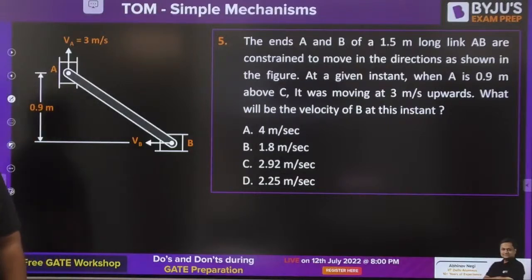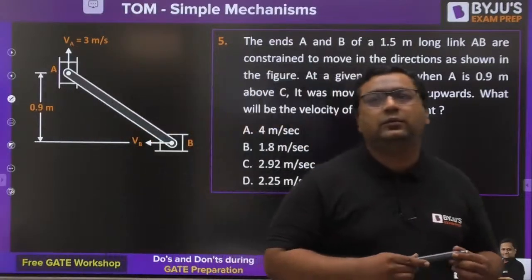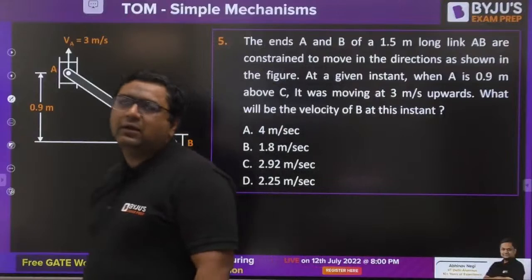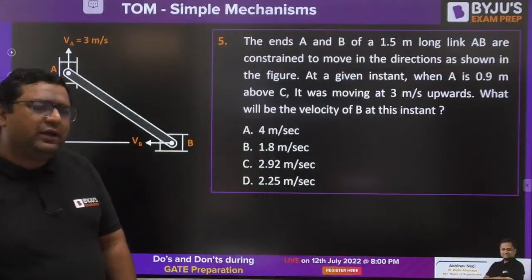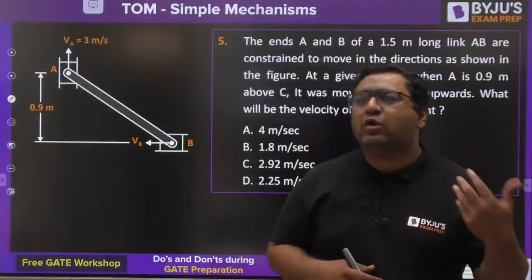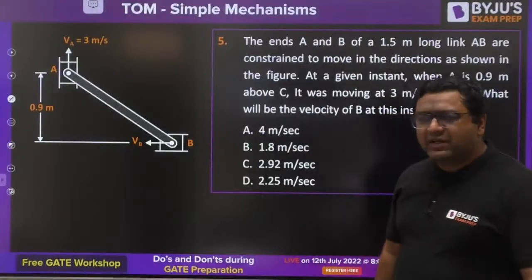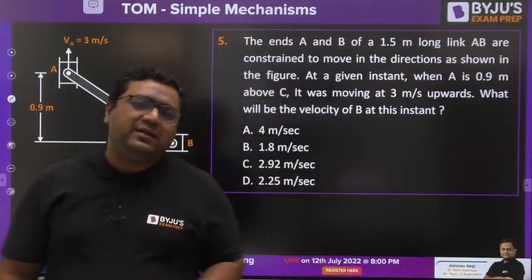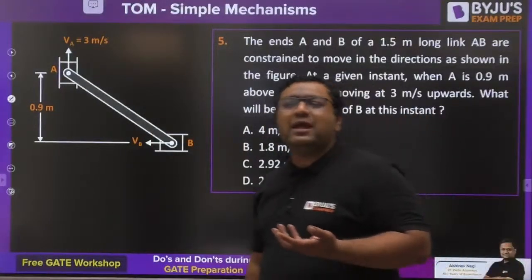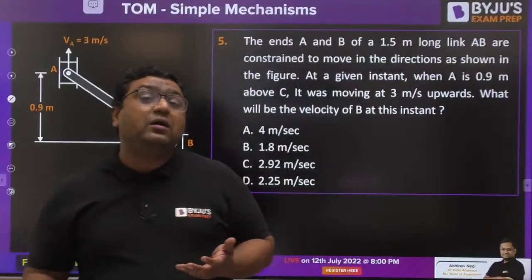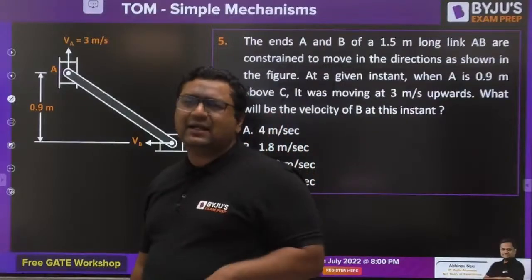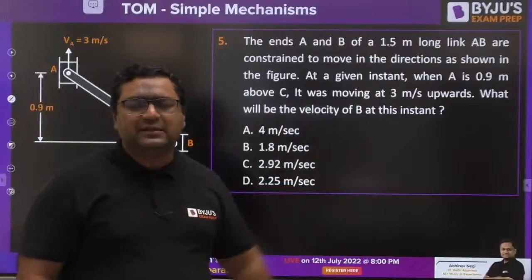Fine. बहुत बढ़िया guys. Piyush ji, that we have discussed. If you are asking me, I will be discussing it at the end, but I already have told you in the classes that whenever the transmission angle is deviating from 90 degree, then output torque is getting reduced. So if transmission angle would be having more deviation, then the rotation of output link will become difficult. This we have proved in the class. So as I said, if you have doubt, for you I will be discussing at the end.